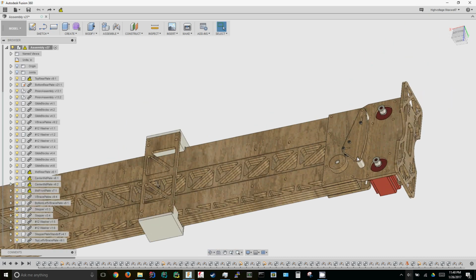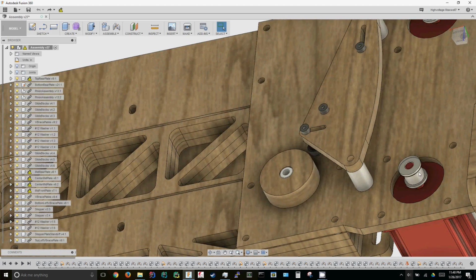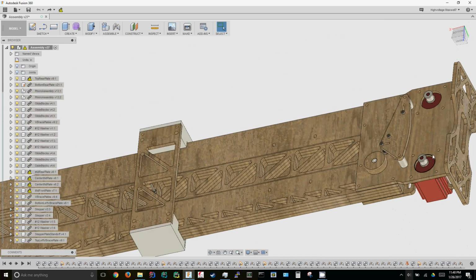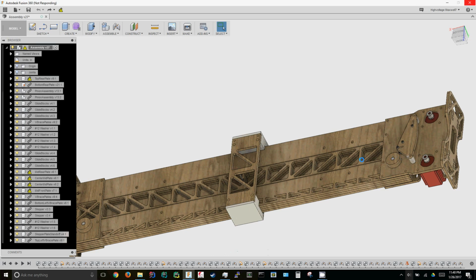But the idea is that you have little belts, just like GT2 timing belts, and then there's this weird serpentine pattern I had to do to get the belt from the stepper to go around these two pulleys here and here at either end, and that's what this plate is for. It organizes that serpentine path, and that is for driving the middle slider.